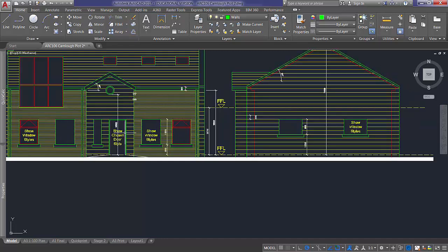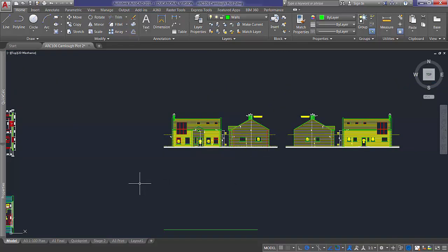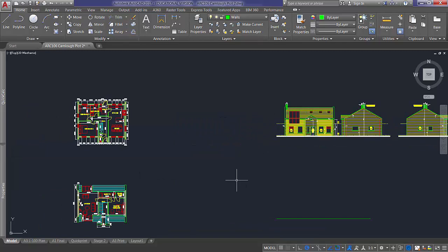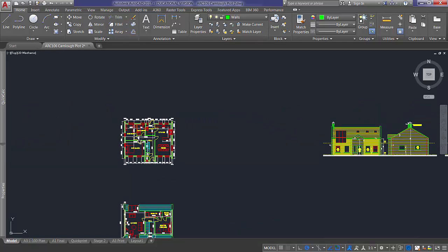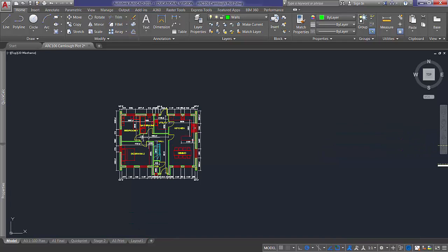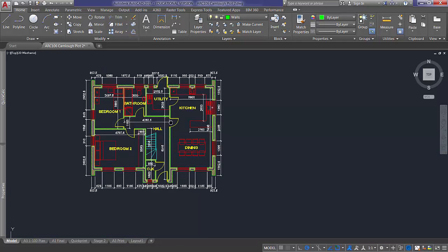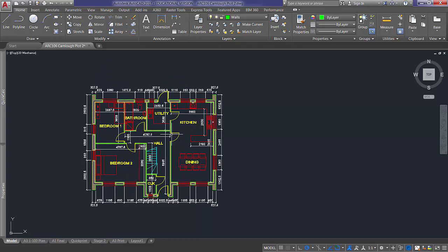Some of the details for the windows and doors are omitted in line with the previous video to allow some variation for those elements. What we need to do is indicate where the section line will be on the plan, and normally you would take that through at the most difficult element of the building. So in this case we should take it through roughly where the front door and back door is,